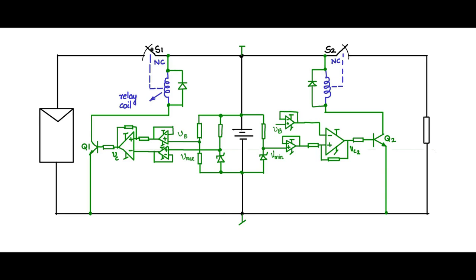Let us say that we would like to replace the relay with a power semiconductor switch like a BJT. So let me erase this portion of the circuit and replace the switch by a power BJT. I am using a PNP because I am putting the PNP on the high side, and I can do rail side switching. So let me put a resistance like this, and I need a resistance here between the base and the emitter.